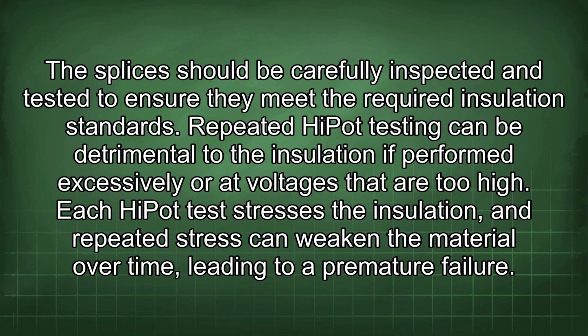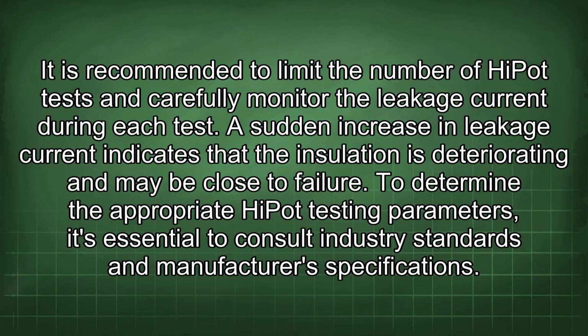Repeated HiPot testing can be detrimental to the insulation if performed excessively or at voltages that are too high. Each HiPot test stresses the insulation, and repeated stress can weaken the material over time, leading to premature failure. It is recommended to limit the number of HiPot tests and carefully monitor the leakage current during each test. A sudden increase in leakage current indicates that the insulation is deteriorating and may be close to failure.